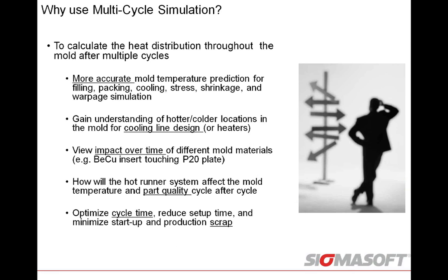So we can take into account the mold plates, the inserts, pins, really everything that consists of that mold in the simulation. And with that, gain an understanding of where the hot locations are, where the colder locations are, and get some guidance for actually designing your cooling system. If you know where the hot spots are, then you have an idea where to put your cooling lines, or where to put a baffle or a bubbler, or even some sort of thermal conductive material.